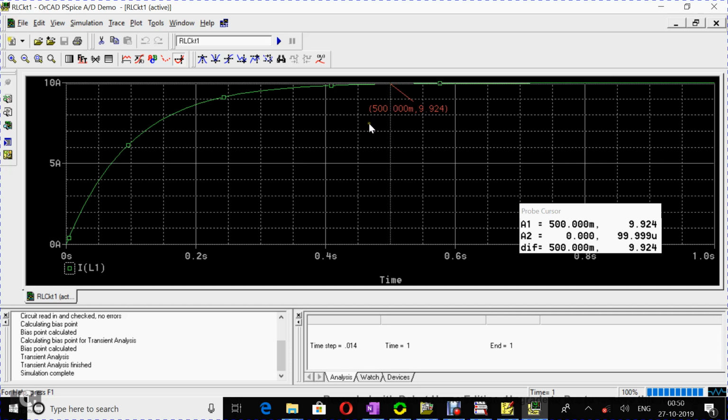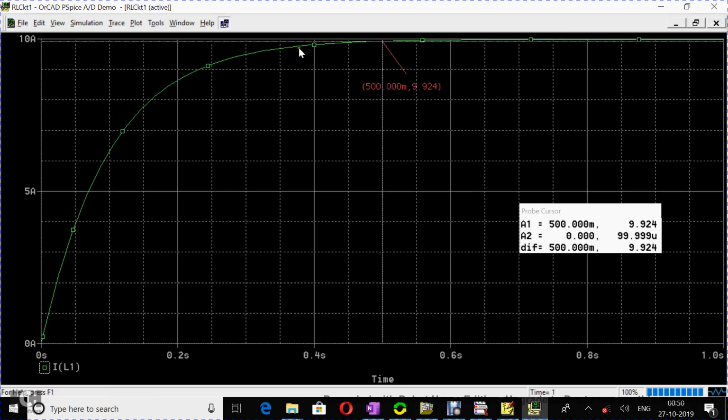So now we can change R and L value, and also we can determine a different time constant, and depending upon that time constant we can identify fifth time constant and verify whether the current is reaching the same value or not, like 99 or some higher value. Okay, so as here, we can say clearly, there are some disturbances in this waveform. It is not smooth, so sometimes this value will be 99 point something, 243 or 4, etc. Okay, what is important is whether it is reaching 99% or higher value. Okay, thank you.